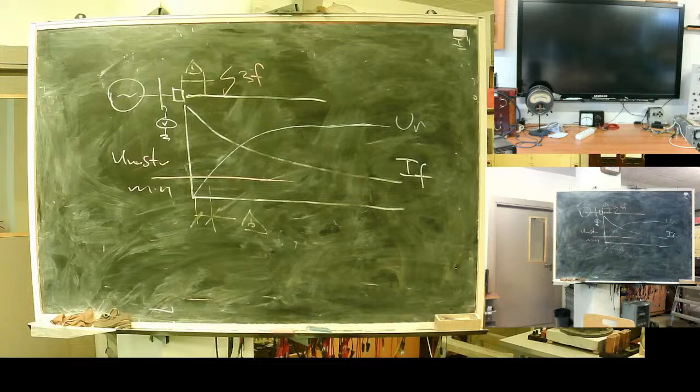But if everything is organized well, all this portable earthing, you saw this three-tailed cat, one long and three short, three for phase and one for earth. They all should be stored with logs, and responsible person who has a right to operate power switch should check them. 1, 2, 3, oh, one missing, where is one?